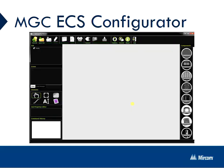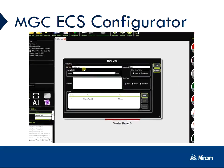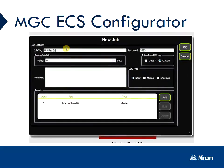Let's start out by creating a new job. Moving your cursor to the top left-hand corner of the configurator, select New Job. A new job window will appear. At the top of the window, you'll have a tag where you will add a job name. You also have the option to change the password from the default 3333 to something of your choosing, up to a total of 22 characters. Moving on, we have a paging inhibit delay, which goes up in increments of 10, and will delay the ability for someone to use the microphone or microphones for the set duration. If you wish not to use it, leave it set at 0.